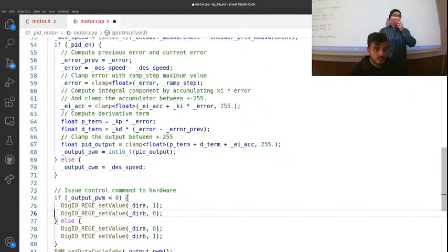And what's the benefit? Stability. You don't have overelongation effects, and you don't stress the PWM that much. Otherwise, if you observe the output of the PWM, you might have banging up, down, up, down. Then what you lose is the reactivity of the system, and what you gain is in the control that you send to the PWM. Otherwise, you tell the motor go up, it goes too much up, then go down, and you get something that you don't want. You are more gentle with your electronics. You get stability at the cost of response, because by using this ramp you don't reach the target you desire immediately, you have to wait a little bit more.